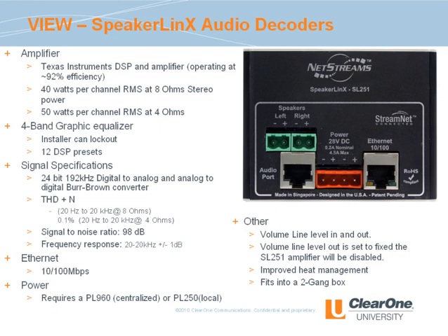Which brings up another design note that is covered in more depth in the technical certification training, but is worth mentioning here. Any device with a processor, be it an encoder or a decoding device, will generate heat from its processor. Keep that in mind when you are planning on where to place a device, especially in areas with insulation that may need to be kept away.